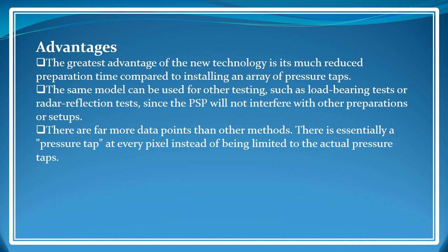If you want to install pressure tap arrays, you have to install every pressure tap and make it an array. It takes a very long time and so much cost. The same model can be used for other testing, such as load bearing tests or radar reflection tests, since the PSP will not interfere with other preparations or setup.